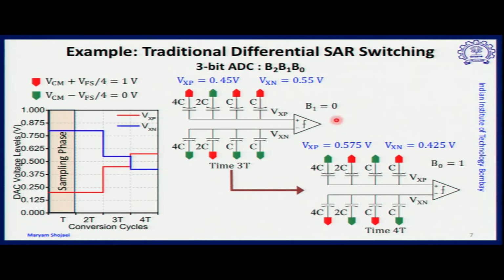So here, in fact, this example is the worst case for energy consumption, because we will have the maximum number of switchings, because every time the decision which is made is opposite to the assumption, and that's why the energy consumption will be the worst case condition.